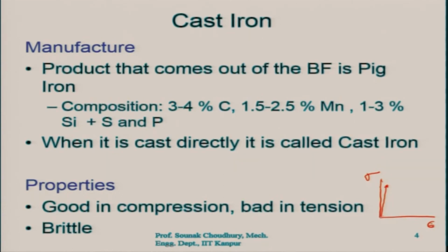This is for the mild steel, for example, the ductile material, and this is for the cast iron. Now for the brittle material, since they break here, they cannot withstand yielding. So, beyond yielding it does not exist. Therefore, up to here the stress strain curve slope can be found out, and so on.